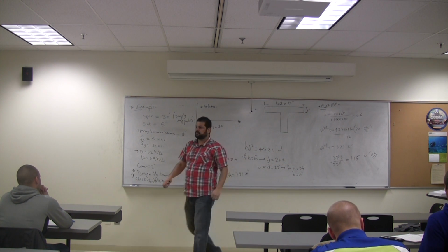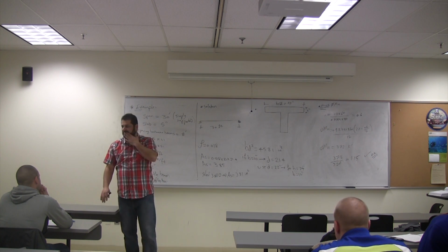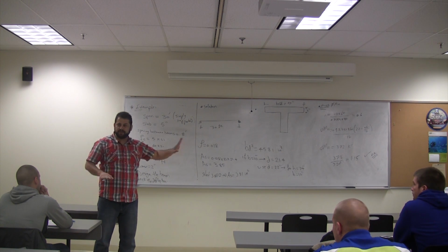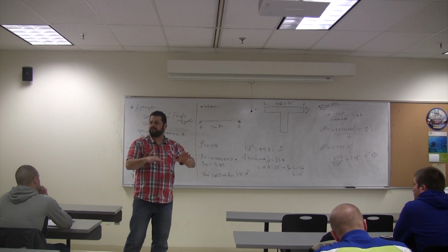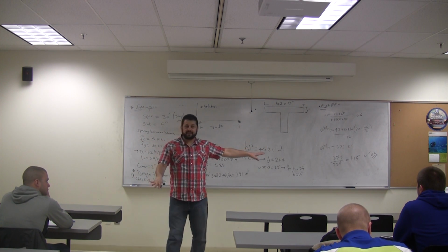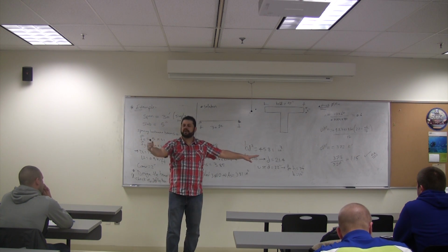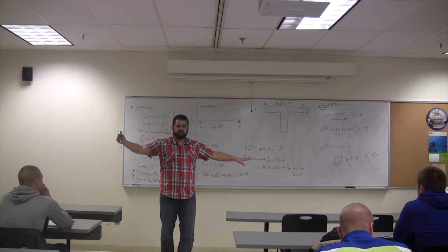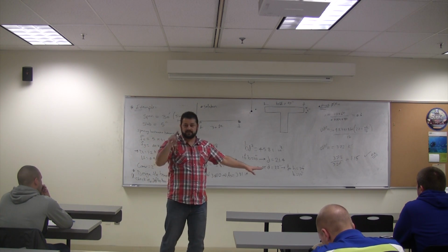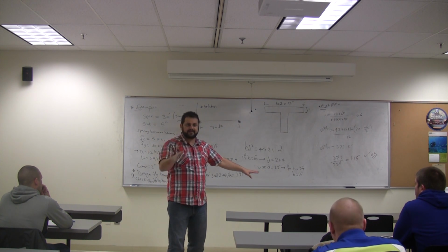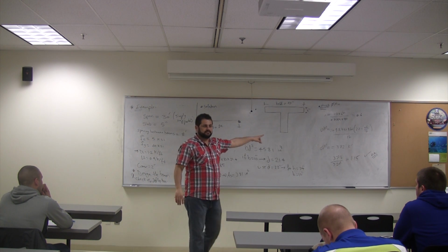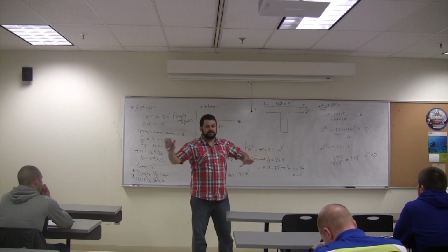What ratio is bad? Look, for this course, I can't just teach you to have 50%. Not more than 15% in this course. Later on, up to 20%. After that, it's really a waste of money. So this is as far as we can go, the 15%. Later on, it's okay if you go to 20% more, but don't go more than that, unless you know the construction guy is really bad, the guy who's going to build it has no clue what they do, and we're going to end up with a concrete that will not give me 5 ksi. See the answer? Depends.